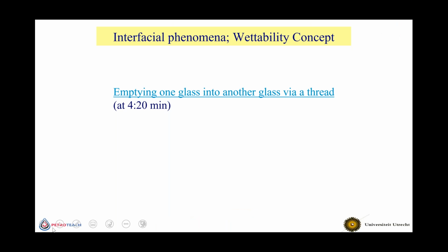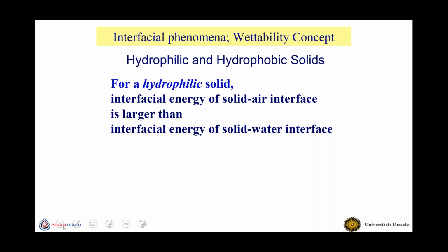So what is the force that is holding that water onto that thread? Now, these are all related to wettability of solids. A solid is said to be hydrophilic if it holds the water. And why does it hold the water? The reason is, again, in the energy. Let me get my pen. The interfacial energy of the solid-air interface is much larger than the interfacial energy of the solid-water interface.